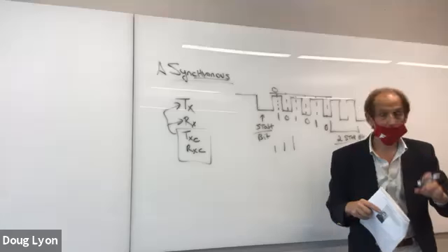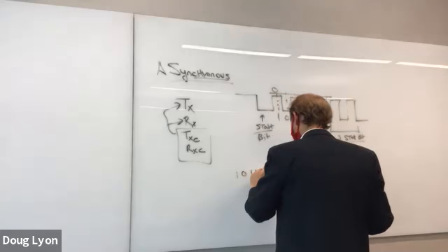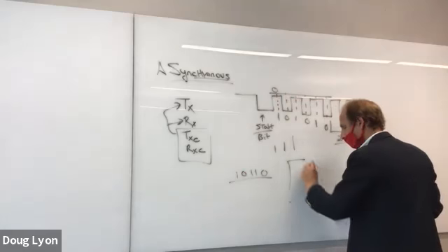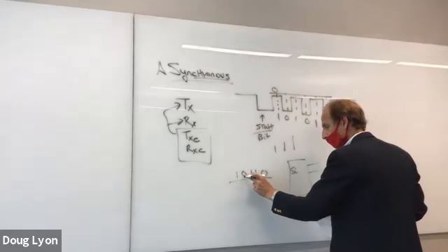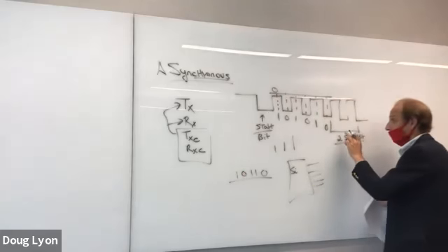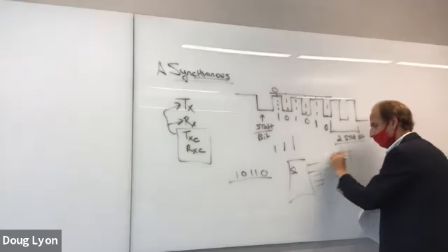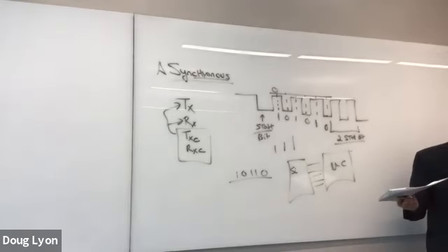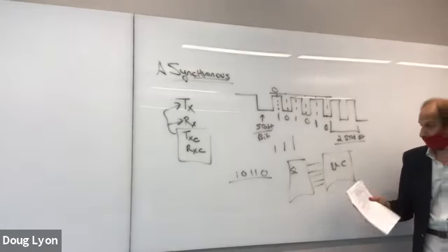the computer. So if I give you 1, 0, 1, 1, 0 in sequence, what I want to do is go into a shift register with a shift input and then output 1, 2, 3, 4, 5 bits. And when they're done, and I'm about to hit the stop bits, I want the microcontroller to grab those bits and put them into a register which gets stored in memory somewhere. Perhaps you're sending strings off to your computer from your serial port.